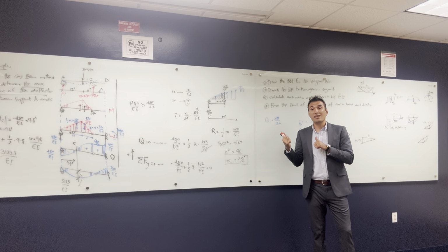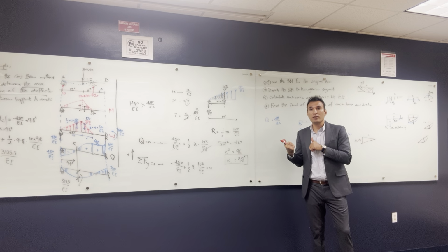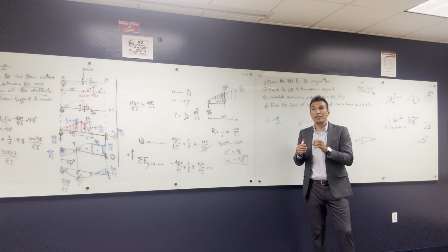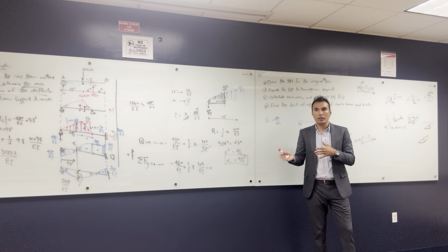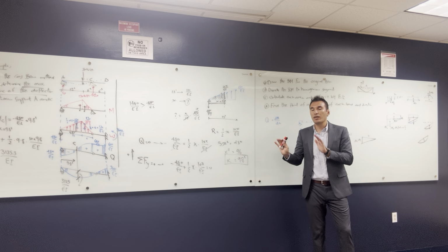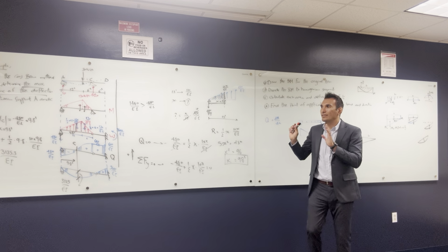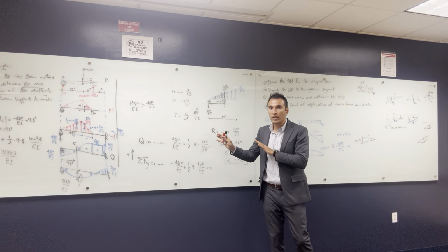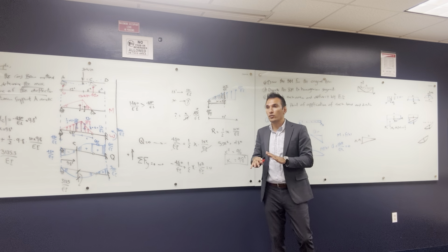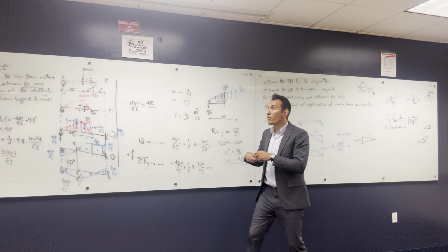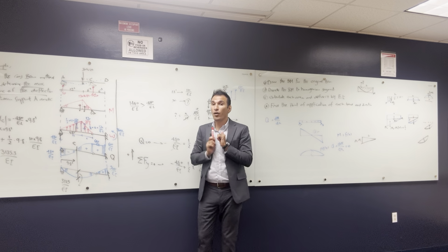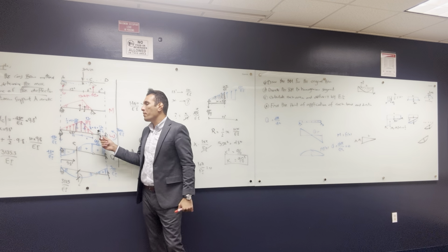What is difficult is the double integration method, because sometimes you get difficult beams, and if you get an integration that you are not used to or not familiar with, it's going to be difficult. But with this one, you get the moment and put the moment on a beam, and I'm going to give you a very simple problem that is determinate and not tricky. You should be able to draw the bending moment diagram on any determinate beam. This is basic structural analysis. And if you put it on another conjugate beam that is determinate, you should also be able to draw the bending moment diagram.